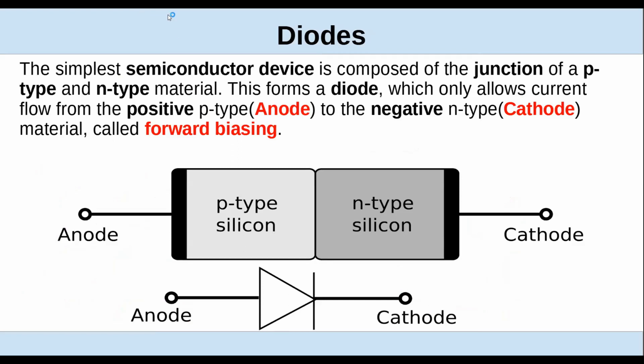They discovered when they put two of these pieces together, a p-type and an n-type, it would act like a diode, just like in the Fleming valve, and it would conduct current in one direction from anode to cathode, the conventional current. The electron flow goes the other way, or charge flow. Because of that barrier between the two, there's a little bias voltage or an offset. There's another name for it, which I forgot at the moment.